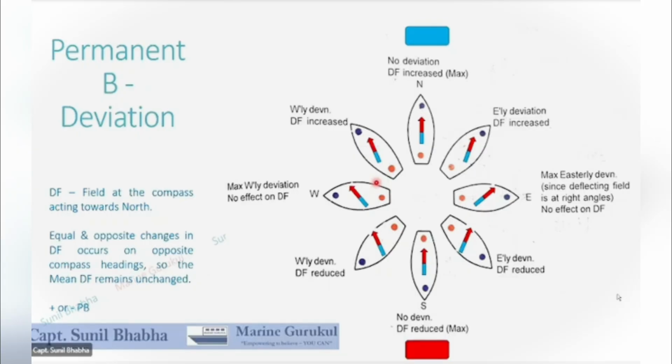The change which happens when you change the hemisphere is in the vertical orientation of the magnetic field lines. In the southern hemisphere, they are coming out. In the northern hemisphere, they are going down. But you see their horizontal component, the H or HF component, is always from south to north, whether you are in the southern hemisphere or northern hemisphere. And our needle here is in the horizontal plane. So we are only concerned about the horizontal component, or the HF component. The Z component is not playing any part in deviation at all.